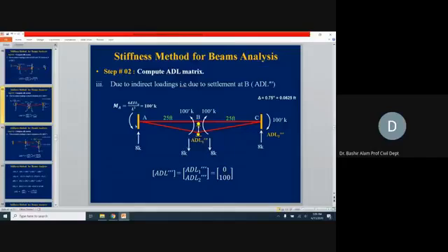The balancing should be in the clockwise direction, and its magnitude we already found is 8 K. So this is giving the contribution due to settlement at joint B. Now you see how we are sliding it down and how towards the support it is 0 now. It is not going to directly affect the settlement at support A and C. So this 100 kip at B, corresponding to D1, we are calculating the actions.